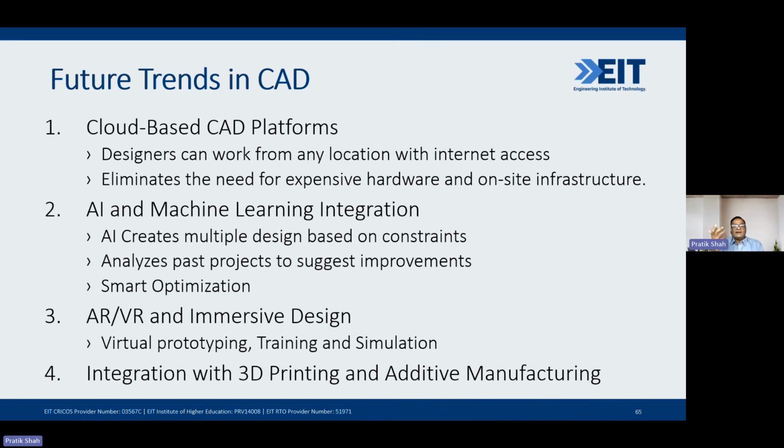There would be AI and machine learning integrated with CAD/CAM systems. I had created one particular component which used basic rough cutting and finishing cutting cycles. Now, if I have similar two-axis jobs which require different operations, this was basically step turning, then a facing cycle, and just knuckle creation.